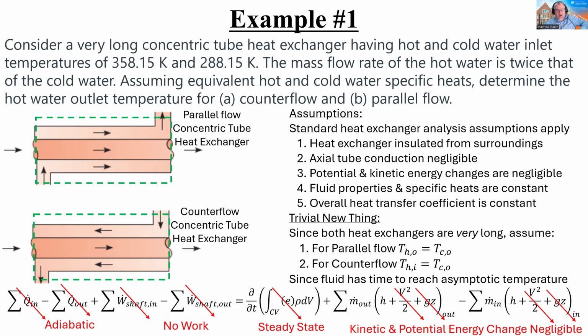Okay, so let's tackle this one. So I have here, as always, whenever you start any sort of engineering problem, particularly energy thermal fluids, you always want a sketch of some kind. I just stole my own figures from the LMTD lecture, so you've seen these before, and I'm just superimposing for parallel flow and counterflow a control volume around the outside of both of those heat exchangers so that we can just analyze them using the first law of thermodynamics.